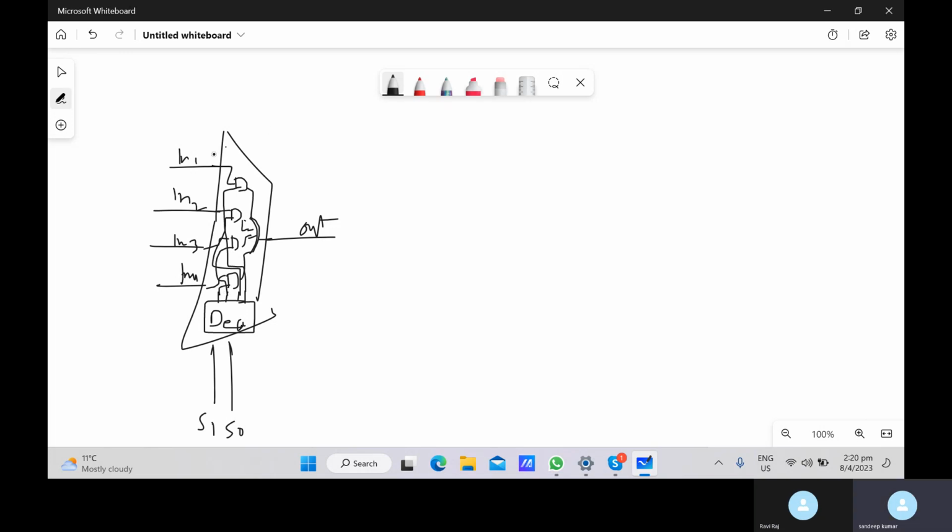This is a generic multiplexer architecture, hardware or logic. So what does it contain? It contains a decoder and an OR structure. Basically, it's sum of products. It will contain a decoder and sum of products. Usually what we need to do is decode the select lines and then create a sum of products using the select line outputs from the decoder.